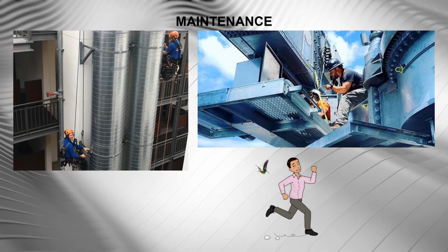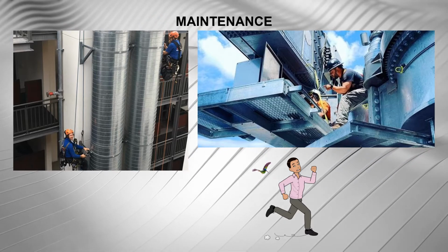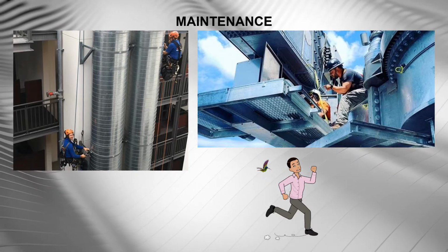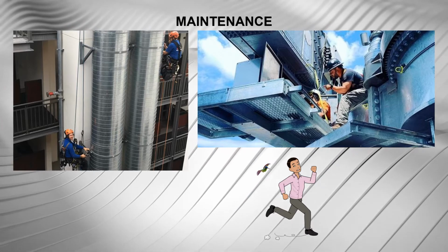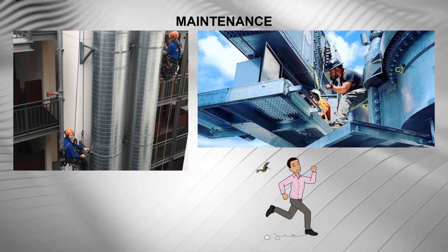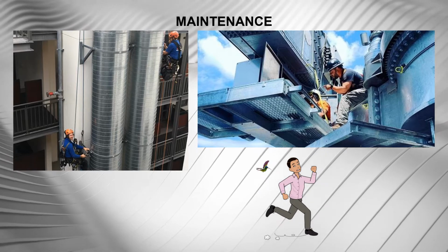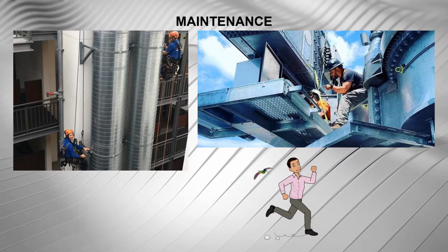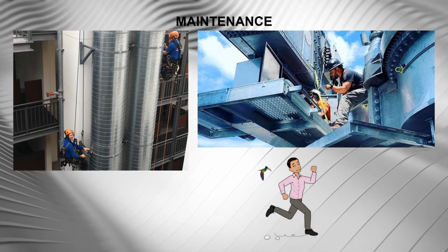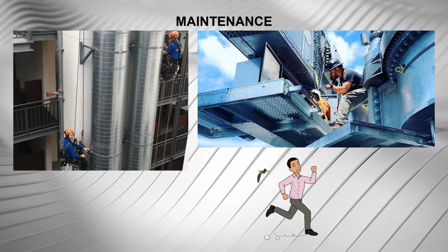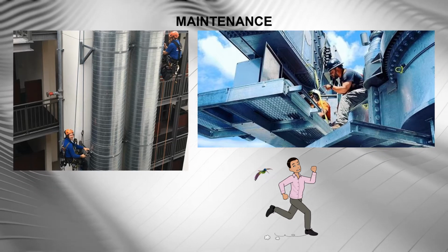Maintenance may conflict with the planned usage of the building, which can easily occur if usage is intensive, as for instance if maintenance requires dismantling or opening up, or if radiography requires areas cleared for safety. Roof maintenance is particularly important. The possible results of overflow due to rainwater outlets being blocked, either by process emissions or by snow or hail, need to be considered in assessing the merits of the roof design, the routes for rainwater disposal, and the maintenance necessary.